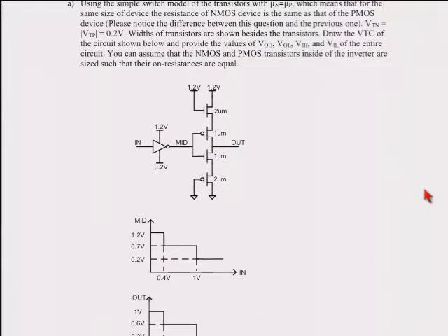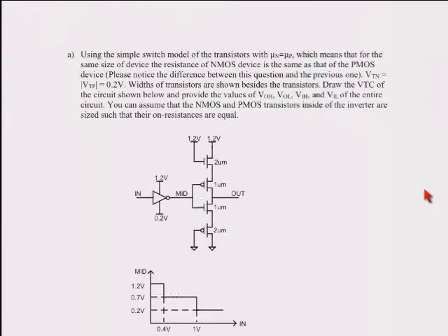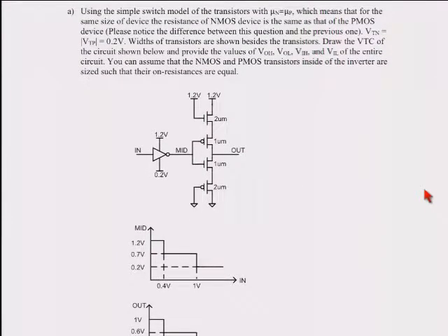So you can see that the NMOS turns on at 0.4 volt, if you're about 0.2 volts above the ground, which is 0.2 volt here. So NMOS turns on, we flip to the middle point, and the middle voltage is equal size transistor, so equal strength. You can approximate this as something that sits at around 0.7 volt, which is the middle between 0.2 and 1.2 volt. It's 1 volt, the middle point is 0.5 volt, 0.2 plus 0.5 is 0.7.